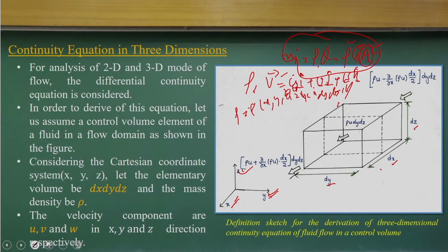That is what you equate as a mass conservation principle. That is how we will get the equations. So, let us look at this derivation. We are looking at a very small control volume with dimensions dx, dy, dz, and it has scalar velocity components u, v, w in the x, y, z directions. If you can see this control volume, I am computing the mass flux.